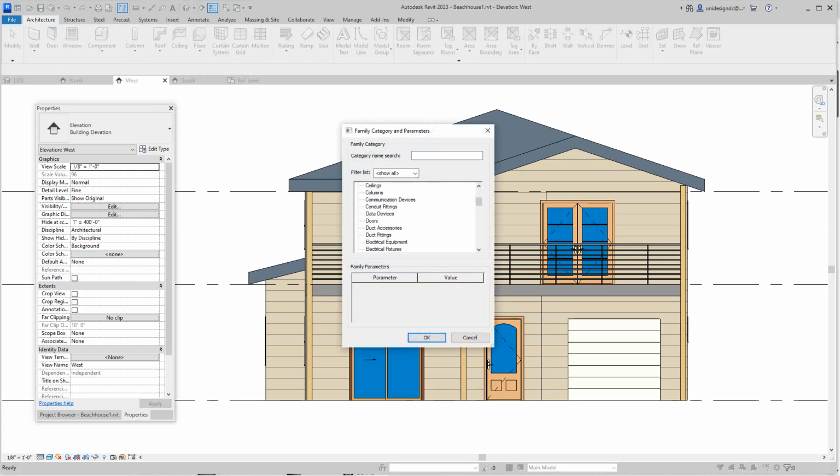And I'm going to go down to Roofs here, because I don't think they have fascia, they don't. So I'm going to go Apply and go OK here. Let's just leave that blank for now to name itself. We could call it ridge or sweep or whatever. Well, it's a sweep, so let's call it sweep.